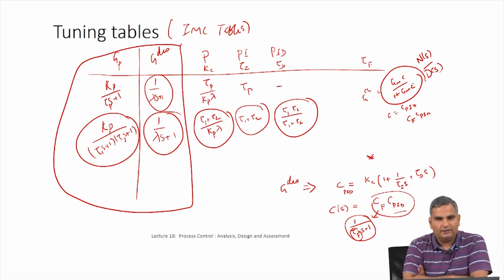And once you have these model equations, we got to what is called the state space form of these model equations, where I have states, which are differential states as far as this course is concerned, on the left hand side. So I get equations of the form dx1 by dt equal to a function of states and some inputs, and dx2 by dt a function of states and inputs.